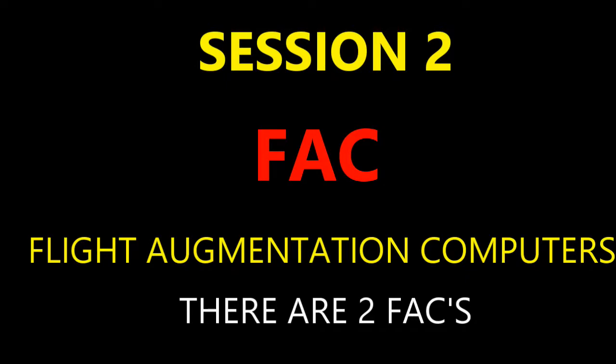All right, we're going to hopefully have the fortunate situation where, when we have our pilot available, he'll be able to tell you a little bit more about the flight phases and inhibitions that are there, and what sounds off, what lights come on, what aural warnings are sounded. When we have different failures, when we have things going outside of those parameters, what all's happening. And this is again having to do with the flight envelope. So, mentioning low aircraft energy, your wind shear, your rudder trim, rudder travel limitation, as well as your yaw damper systems, if there's something wrong there.